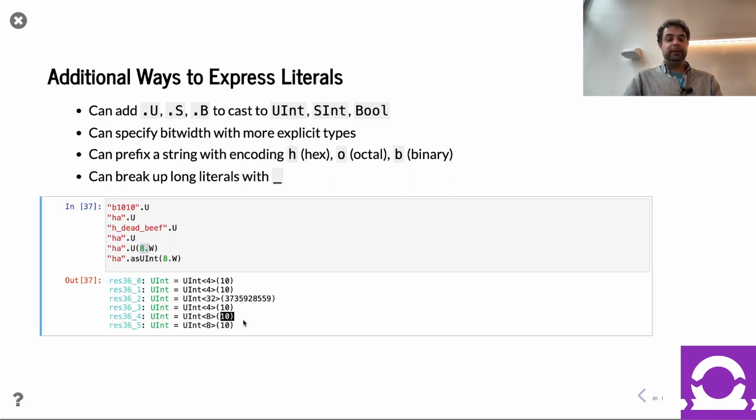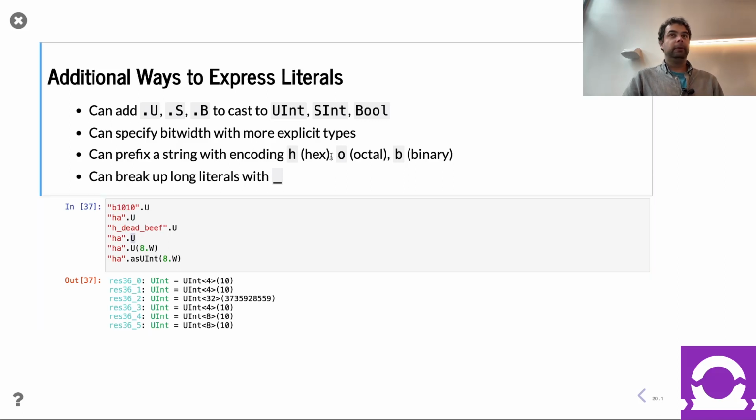Yeah, you got it. Instead of .U, you can say .asUInt. This is kind of more in the flavor of how Scala does things. Most Scala conversions are like .asSomething. But .U is nice and short to use a lot for Chisel. Cool. Any more concluding questions?